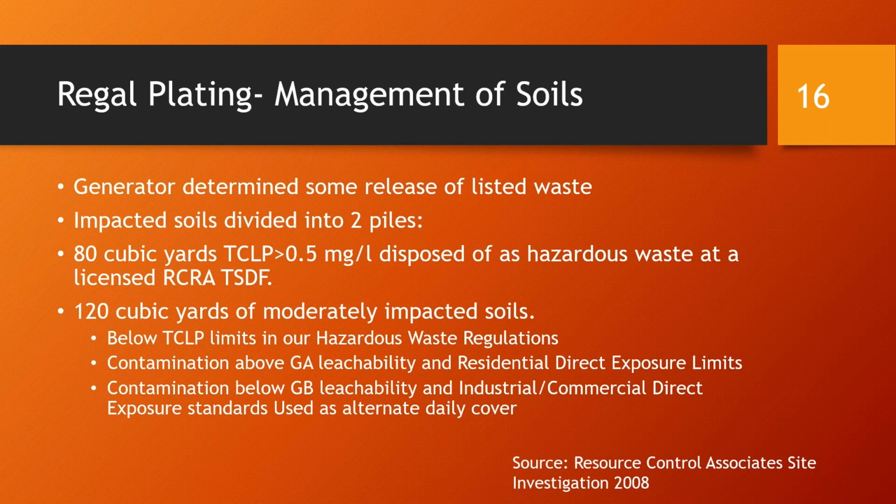So in this case, they asked the state for a contained-out determination. We provided one, and this waste could be disposed of at a licensed solid waste facility. Why? Because in terms of what's the applicable environmental standard, if it met residential criteria, we'd say it can go anywhere, but it didn't. It met industrial commercial criteria. So a lined landfill would be an example of a site where that material is allowed.